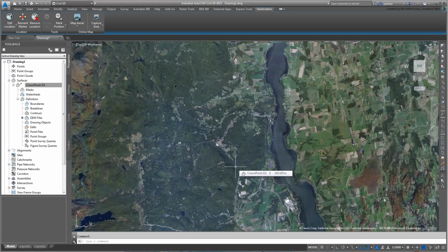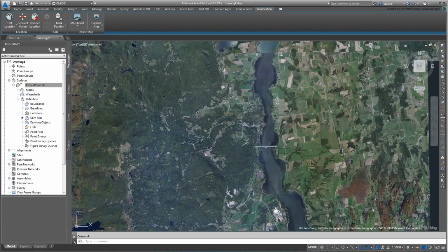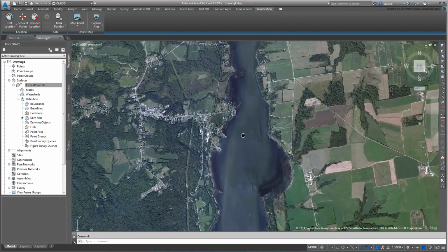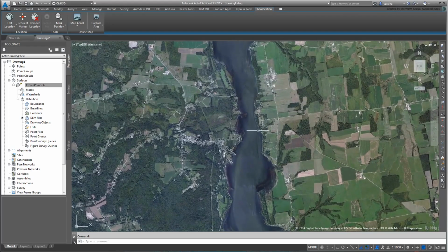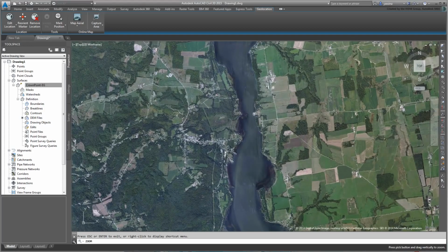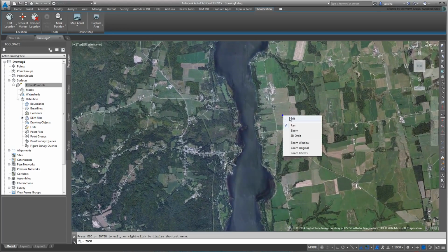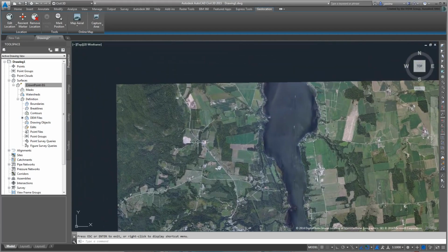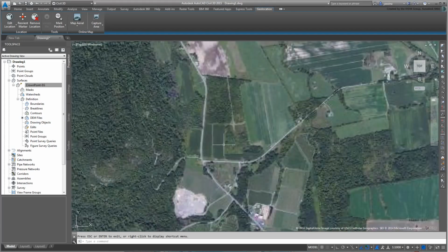Next, you draw a rectangle over the area of interest using the Rectangle or Rec tool. It is important that the area you select here is the same one you defined when you created the aerial image earlier. This ensures that the ground texture image you created maps itself properly to the extents of the created surface. First, draw a couple of lines to define 2 corners for your rectangle.